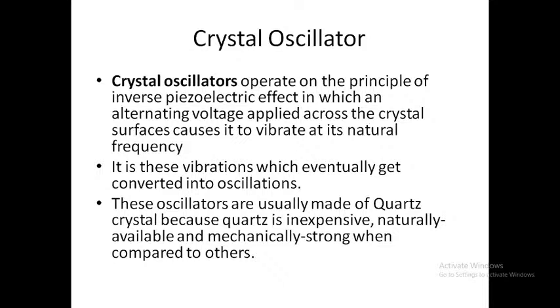So crystal oscillators operate on the principle of inverse piezoelectric effect, in which an alternating voltage applied across the crystal surface causes it to vibrate at its natural frequency. Means what? When you take the crystal and apply an alternating voltage, that is an AC signal, to this crystal, it vibrates at the frequency of that AC signal.